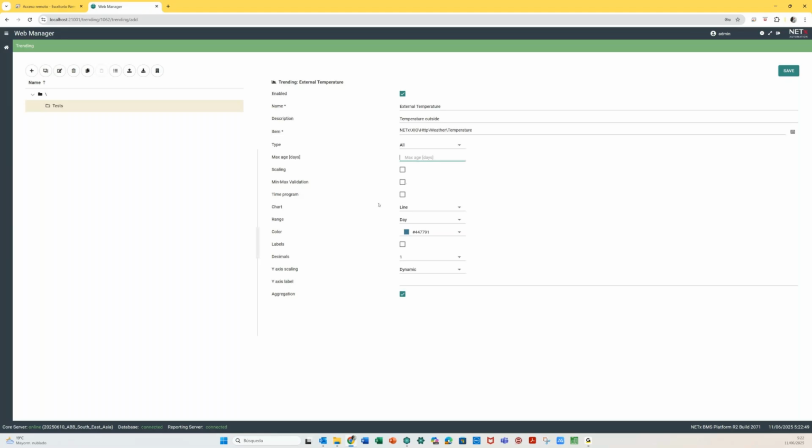You can apply scaling directly. So you can multiply or divide. Divide is multiply by 0.1, for example, which is divide by 10, but normally this scaling is not necessary. But okay, imagine that you get from Modbus a value in integer format, but you know that there is a scaling of 100 times.